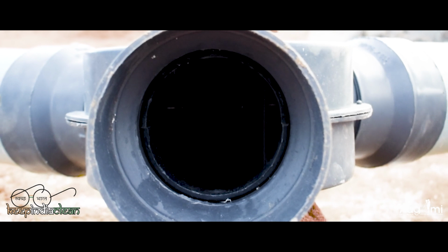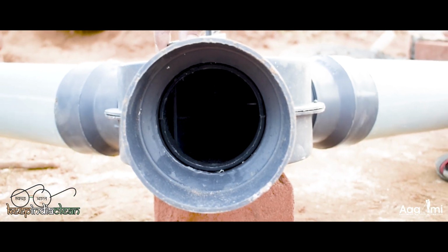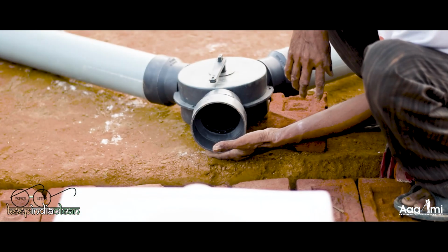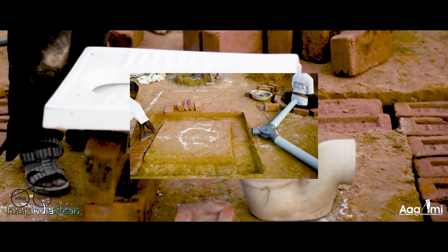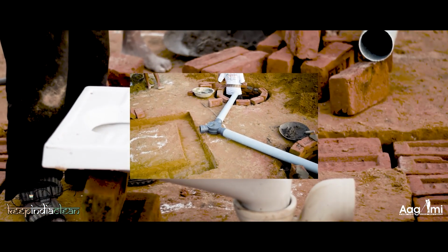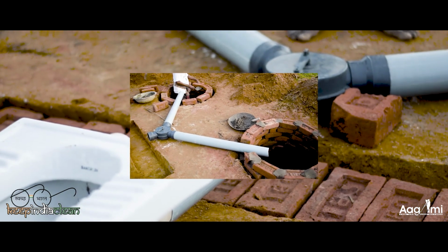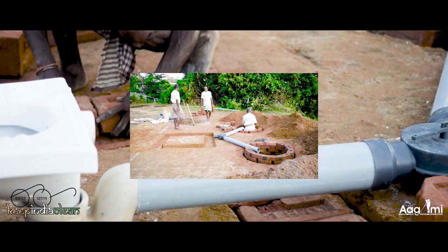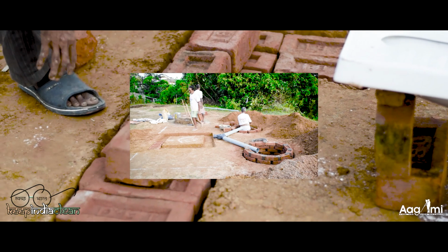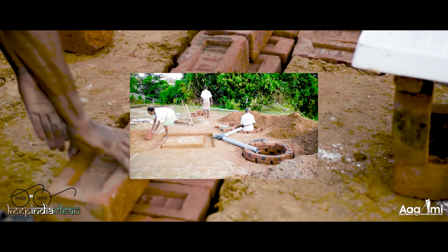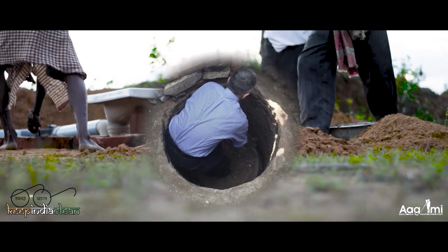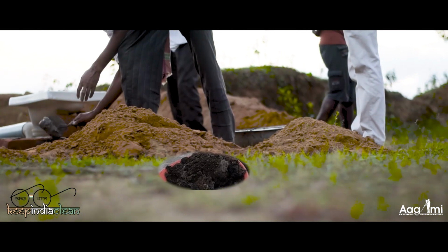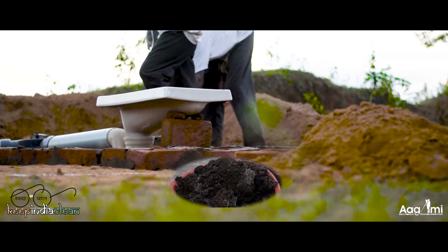First, one pipe of the Y joint of the inspection chamber will be kept open while the other one is locked. In this situation, our faeces is thrown into one pit only, and it will continue for around 6 months. After 6 months, let the path of discharge be changed into the other pit by this simple mechanism of the Y joint, and let it continue for another 6 months. During this second half of the year, the first pit is kept unused and microbes work in it. Finally, at the end of the year, when we uncover the pit, we find the solid dust-like residues which have already been decomposed into manure, organic manure, best for agricultural use.